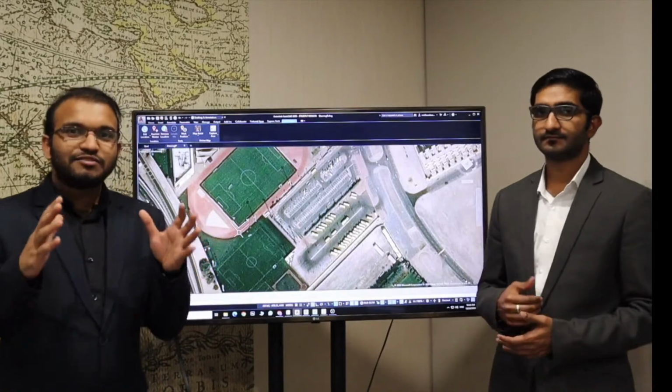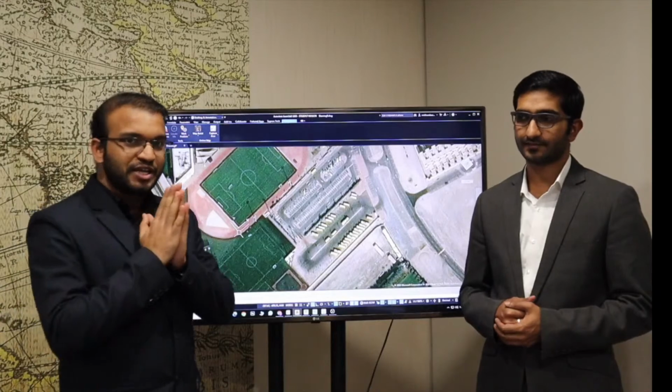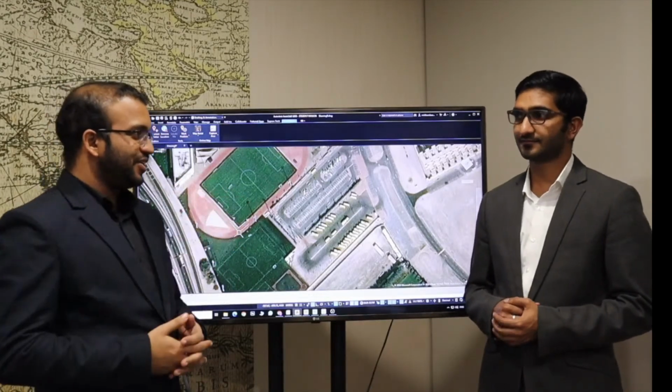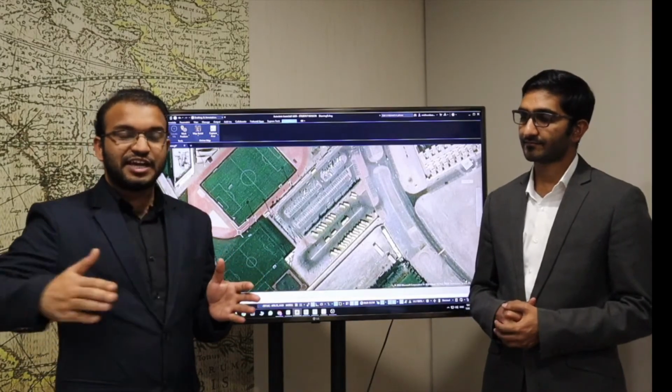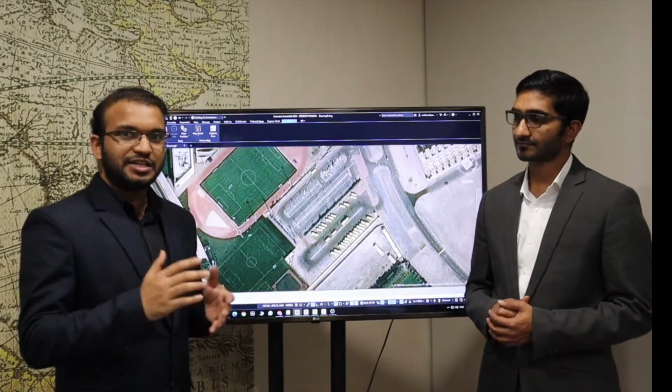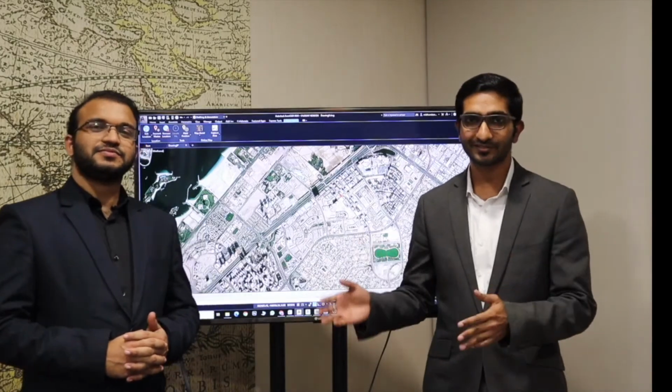So this is one of the major differences between WCS and UCS. When we do a project, this is very important, right? Because in one site you can have n number of projects and buildings with different orientations. So I hope you all understand what exactly UCS and WCS are. In a nutshell, UCS is the user coordinate system, which can be changed or manipulated according to user preference, and we can orient it, while in WCS we cannot change or manipulate it.